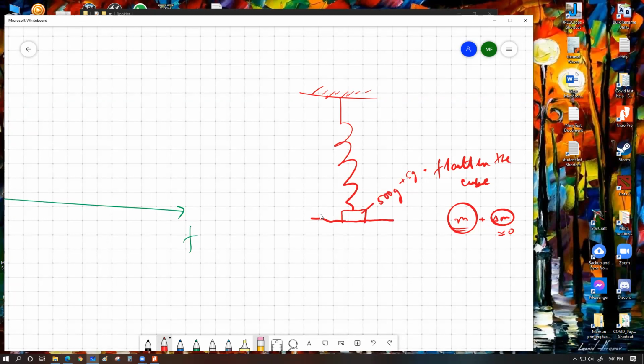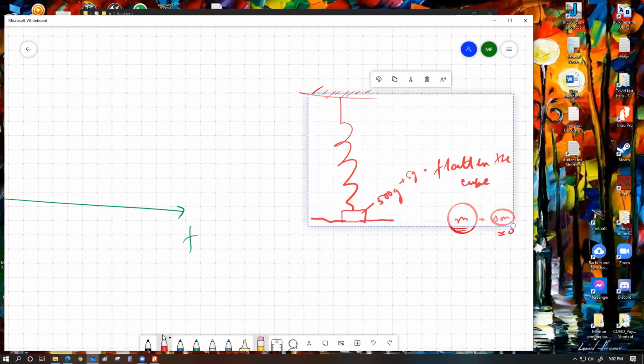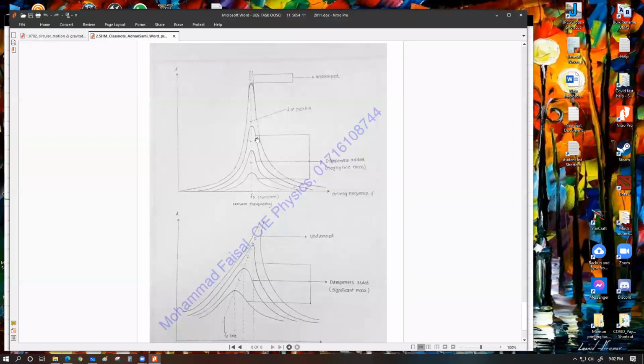So if the damping mechanism that we are introducing has a negligible change of mass, then we can consider that the change of the amplitude is going to happen very much like this, with the mass of the system remaining practically unchanged. We're going to have a lower amplitude, but the object can still oscillate at its natural frequency.